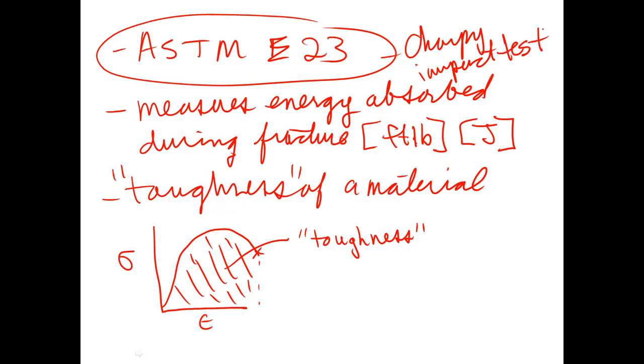They might give slightly different values simply because the rates involved are much different. The Charpy test is a high strain rate test, whereas the stress-strain curve would be a lower strain rate. So in terms of impact type failures, in most cases the Charpy test would be more desirable because it's those high strain rates usually that result in impact failures.